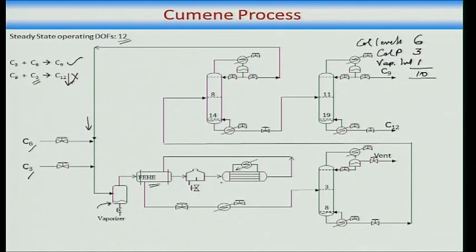The reactor is a shell and tube heat exchanger with catalyst loaded tubes, and it is cooled by circulating coolant at a very high rate on the shell side. So, what that means is that the shell side temperature is essentially constant. Okay. This is what is being shown here. The reactor effluent has its pressure reduced from the reaction section to the separation section pressure. It is cooled in a condenser to liquefy everything that can be liquefied, which is basically C6, C9 and C12.